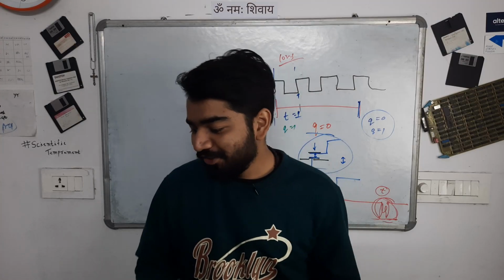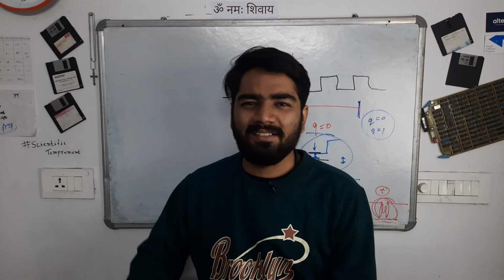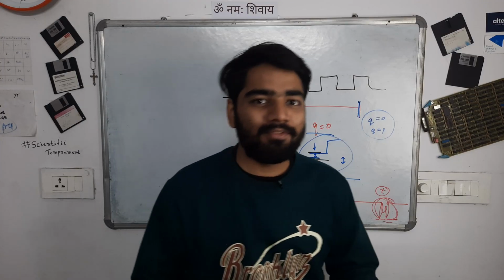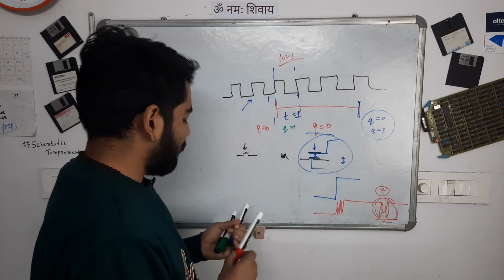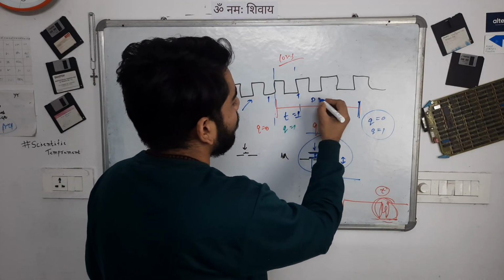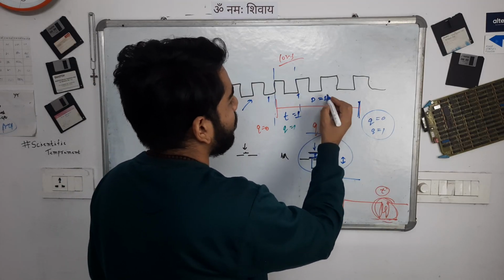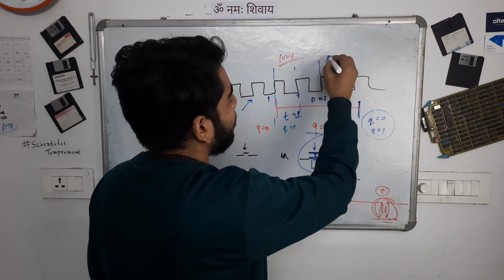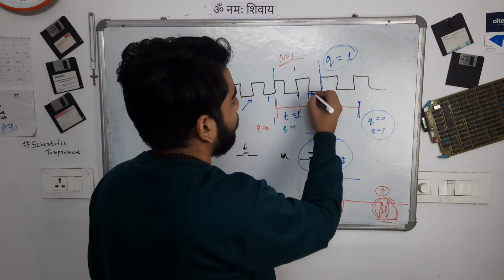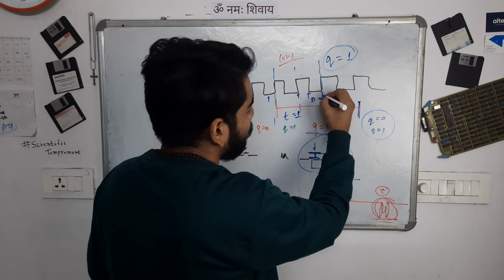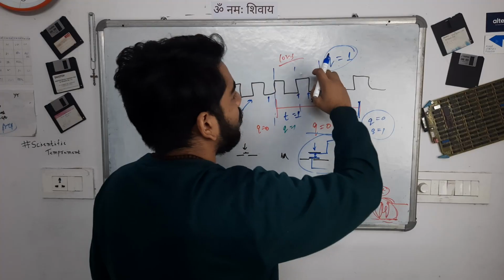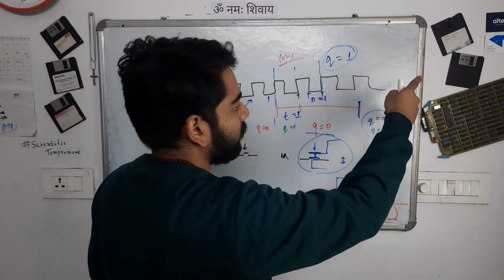So hopefully you understood why this T flip-flop is not behaving the way we expect it to. Similarly for the D flip-flop, since the clock is so fast, if I keep D as 1, the LED will be instantly equal to 1. If I put D equal to 1 over here, Q is equal to 1, because at the next clock edge D will be transferred to Q.